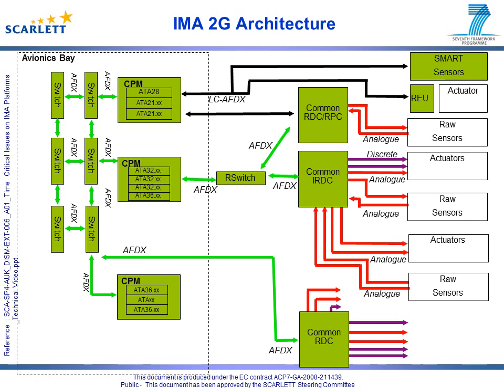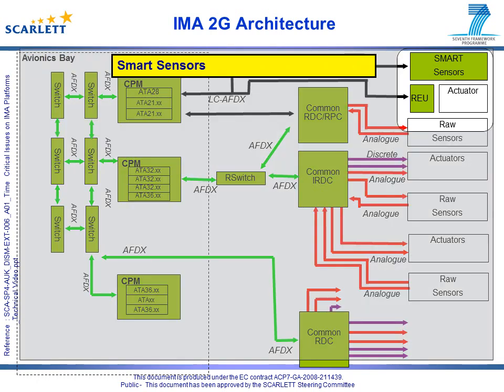The other new concept here is the smart sensor or actuator. Essentially, this is the raw sensor or actuator with added functionality in terms of limited processing, maybe data loading, and a digital data bus link, as opposed to an analog or discrete link. Smart sensors or actuators have a standard interface but may have different implementations. Although this allows components from different suppliers to be used, it does resist the move to common resources.